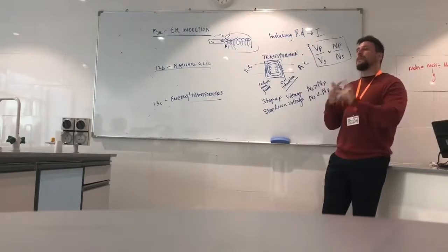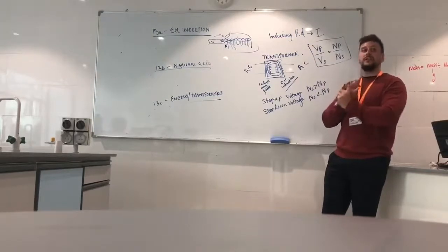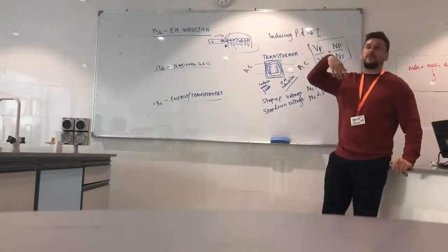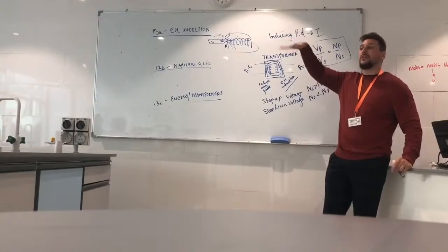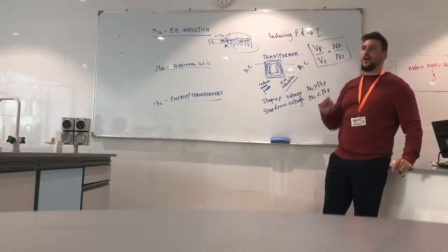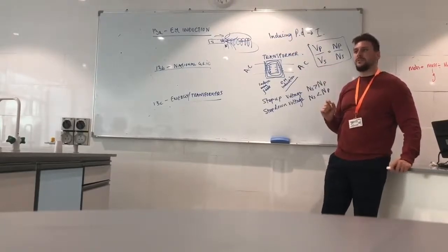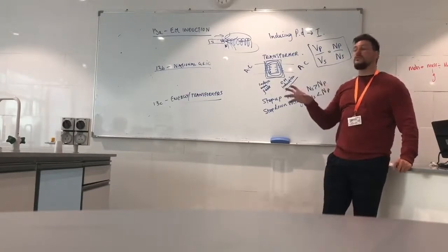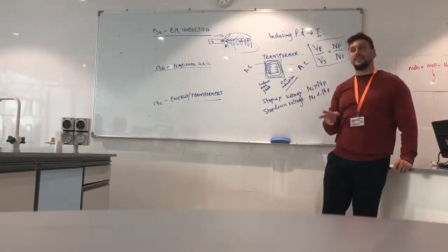We step up immediately to 400 kilovolts for the transmission lines, which are the cables that transport the electricity across the country. Why do we step up to such high voltages? To reduce the amount of energy wasted by heating in the cable.